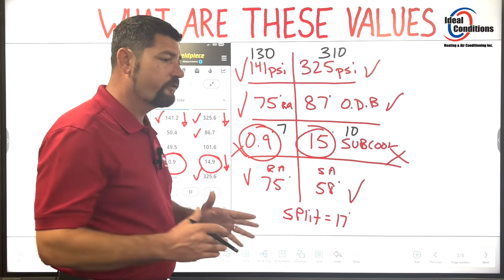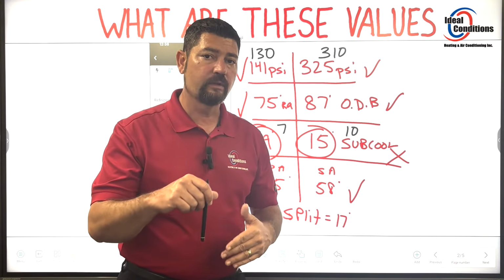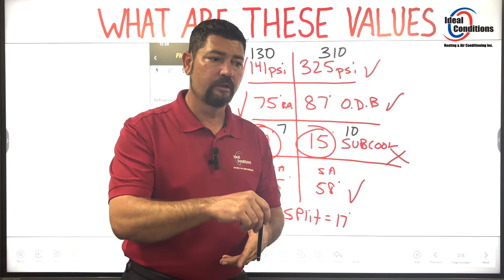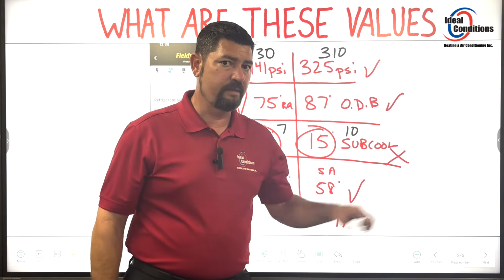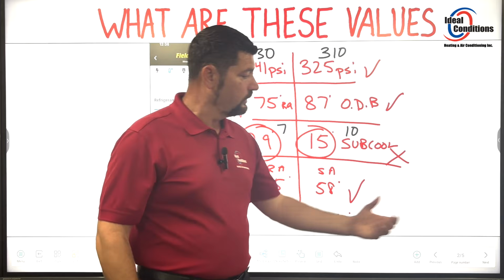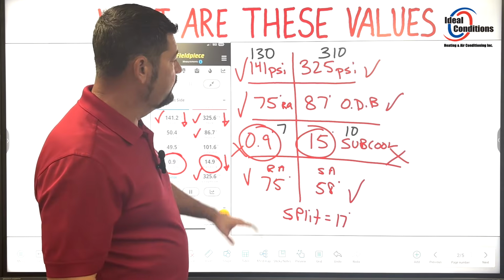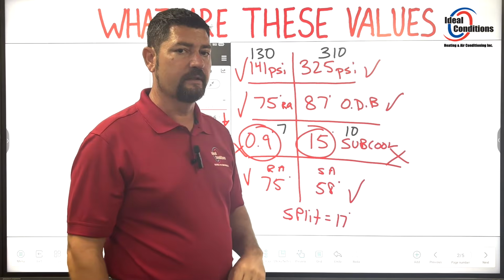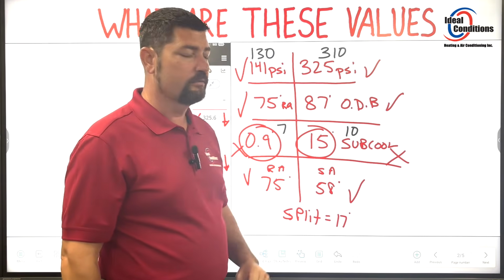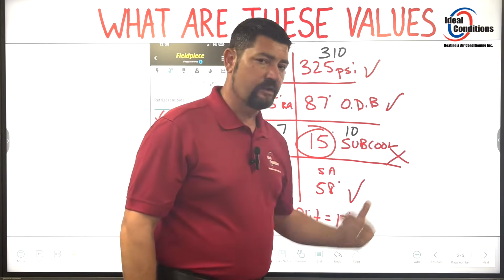A recovery machine has a condenser coil, condenser fan motor, and a compressor. So does my condenser. So if I'm running, the condenser becomes the recovery machine. So I can remove a little bit out. Now let's just say I'm doing that and these numbers do not correspond. This is the 1 + 1 = 2, right? Then I have to go to that next step.